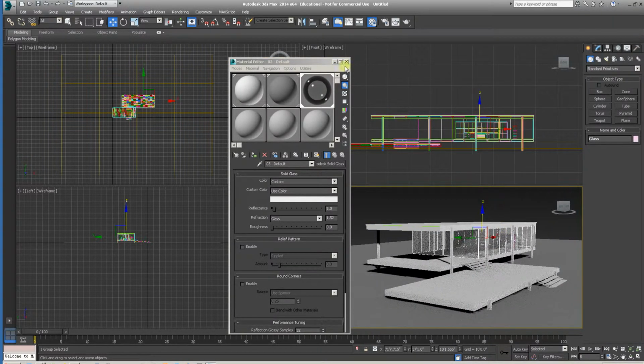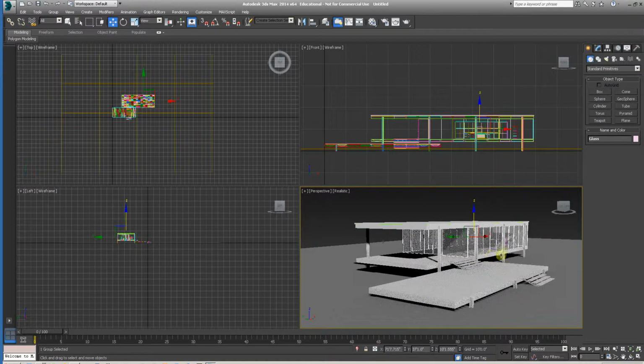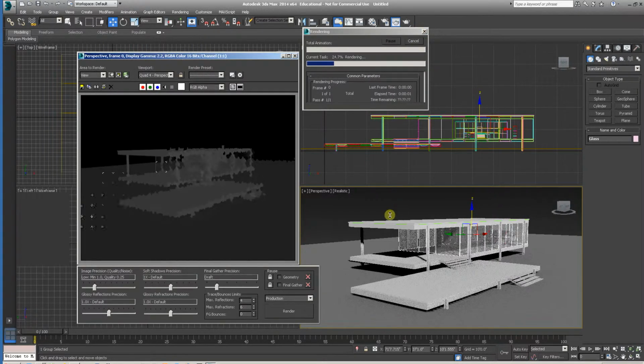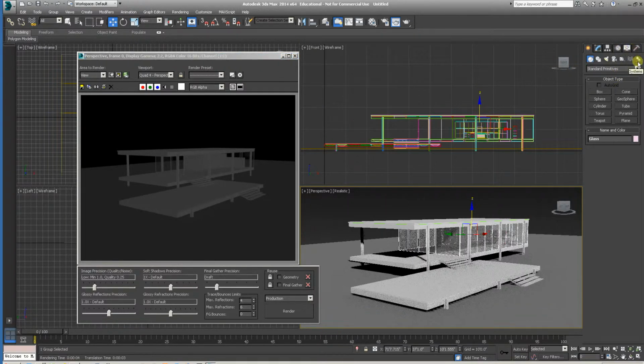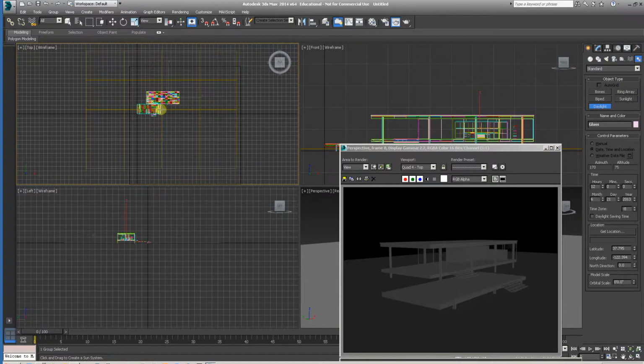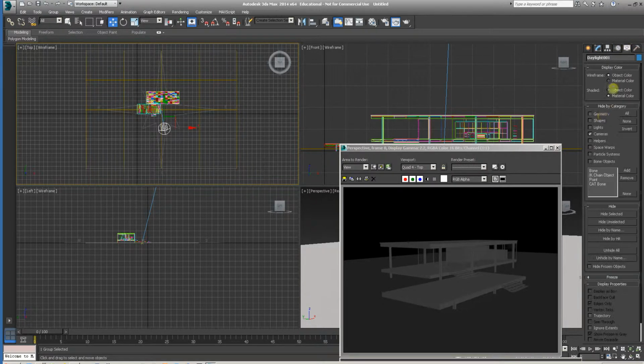So we've got our renderer set to, not V-Ray, but mental ray. If we render right now, there's no lights in the scene. It will kind of just give you a flat gray scene. There's a couple options for rendering. What we're doing now is a daylight render, so I'm going to go to the Create tab where we picked geometry of that plane. I'm going to go to these other buttons. There's Shapes, Lights, Cameras. I'm going to go to Systems where I can find a daylight system. It's highlighted blue, so that means it's active and waiting for me. I'm going to click a couple times, and let me start displaying these cameras.